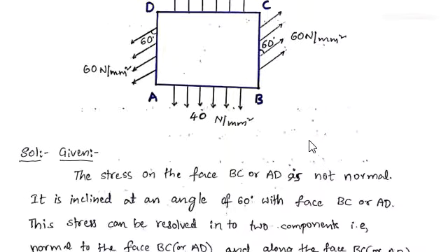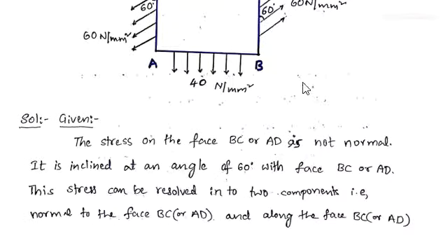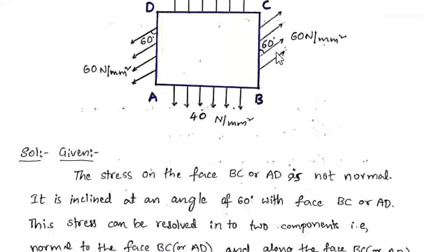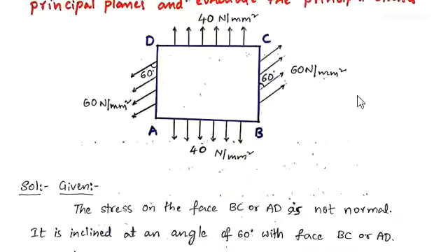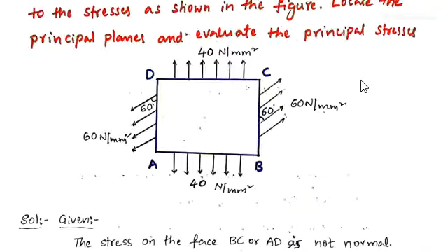So here, I told, we'll resolve this. This is not normal, so we'll resolve this stress into a normal component and a tangential component with respect to this plane BC, and we'll find out the values of principal stresses by using the formulas available.